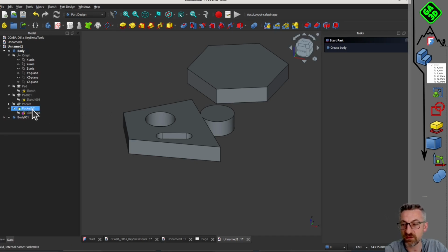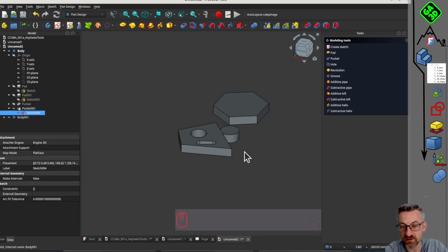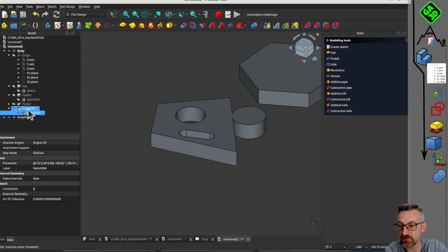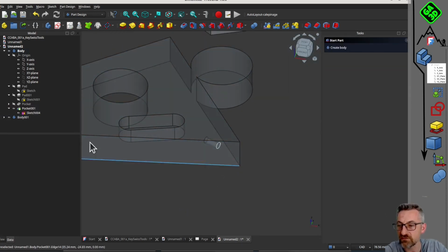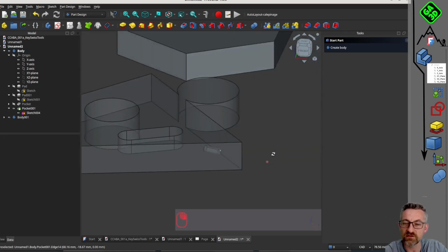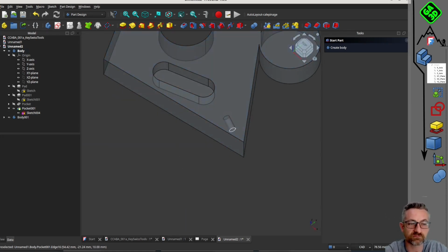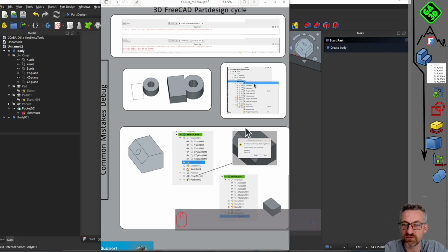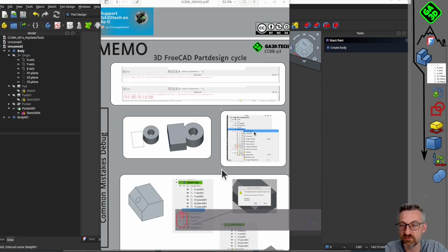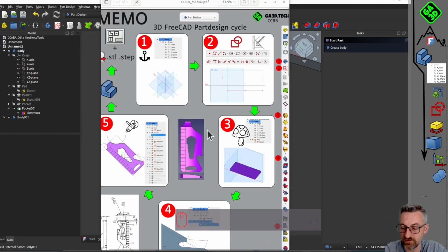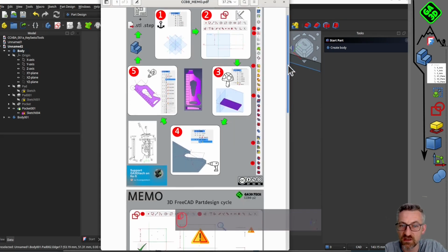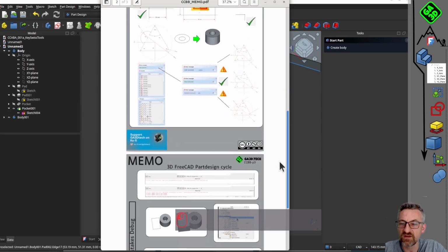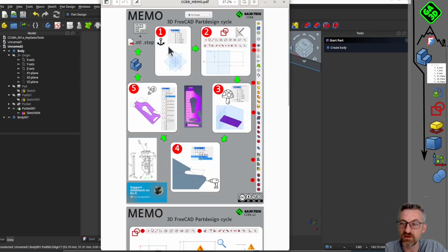Now in FreeCAD, they've addressed this, not really a bug, but something that could be problematic depending on your workflow. For me, it was never really an issue, but they've improved the way attachments work. However, if you attach something to a face created by a chamfer operation and then delete that chamfer, the face is no longer there, so the attachment is lost. There's nothing you can do about it. So these are things you need to be careful about.